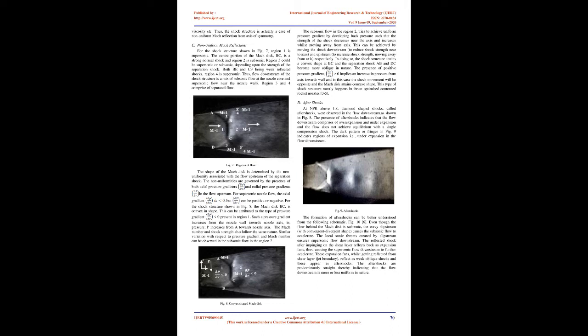A shear layer originated from the separation point, whose thickness increased with the increase in NPR. This shear layer caused the flow to remain detached downstream and continue as a free jet. A slipstream, known as the entropy layer, emanated from the triple point and continued downstream. A better comprehension of both shear layer and slipstream can be obtained from the schematic in Fig 6. Fig 6. Separation schematic.